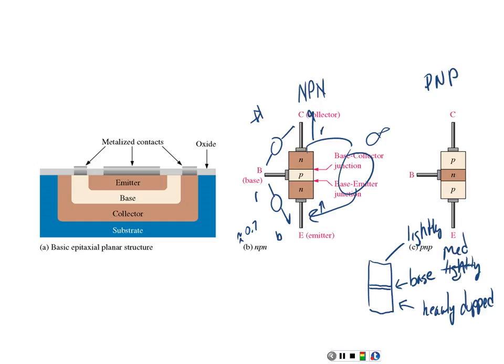So no matter which direction I put the lead, let's say I put the black there and I put the red there, well, the red is still pulling the electrons that way, right? So when you check your collector to emitter, you should have an extremely high resistance. Most digital meters will show it as an open. But you got to be careful.